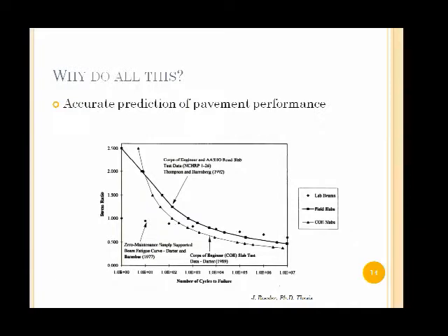And you can see that it gets, and this is a fatigue test, but there's a huge discrepancy between just a simple flexural strength value and the actual performance of a pavement. So we need something better to quantify how this pavement's performing and whether or not it's going to crack and fail at a given stress level.